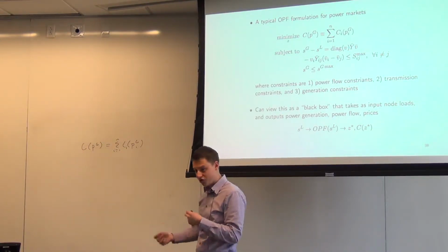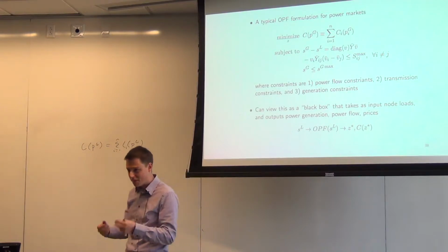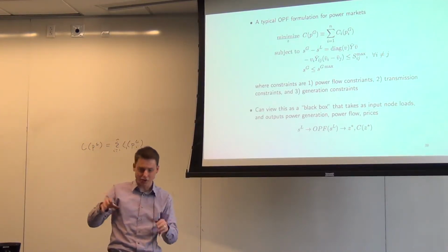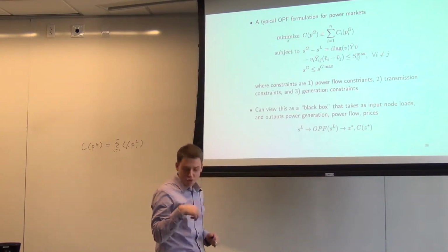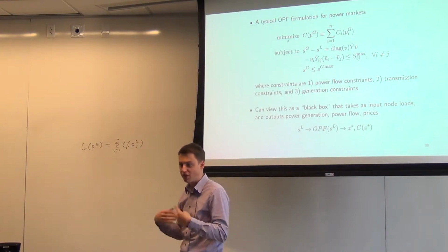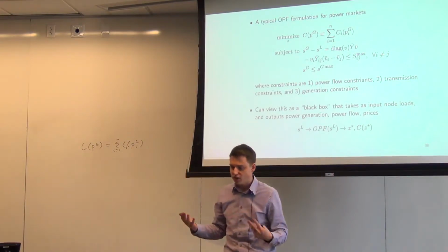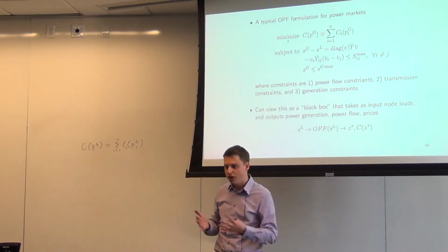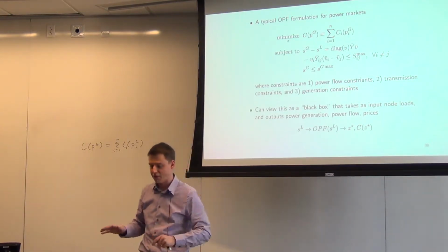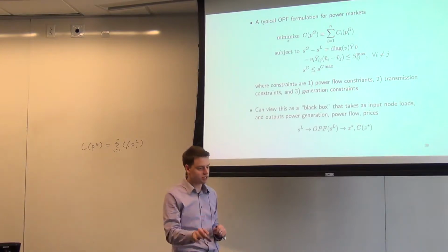You can control the voltages a little bit by turning the generators, essentially putting more current through those exciter magnets in the generators. You can certainly control the power to a certain extent. That's the real power they generate. You control the reactive power kind of indirectly. But the loads of the system are really beyond your control, at least in this setting. We're not assuming we have demand response or anything like that. There's loads in the system, and we do not control those.